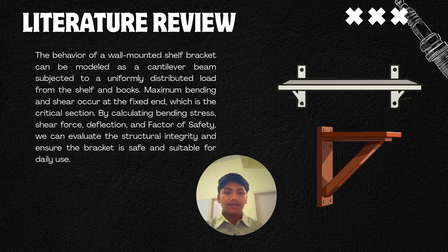Next, literature review. The behavior of a wall-mounted shelf bracket can be modeled as a cantilever beam subjected to a uniformly distributed load from the shelf and books. Maximum bending and shear occur at the fixed end, which is the critical section. By calculating bending stress, shear force, deflection, and factor of safety, we can evaluate the structural integrity and ensure the bracket is safe and suitable for daily use.